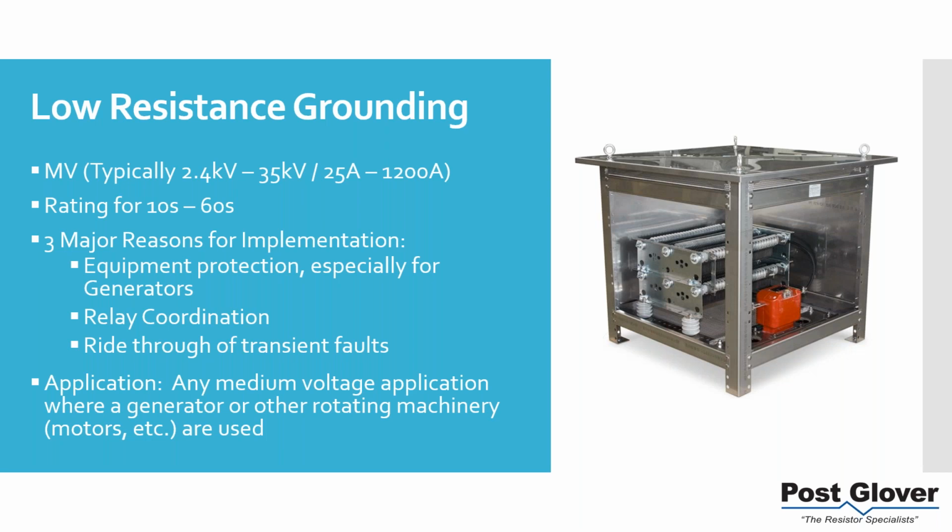When I'm talking about a resistor in terms of current, what I'm actually saying is the amount of let-through current. So if you have a certain resistor and it allows 400 amps of ground fault to flow, I would call that a 400 amp resistor. It's a lot easier than trying to figure out the math in your head and just going by the resistance. So just in case somebody didn't know that, that's what it is.